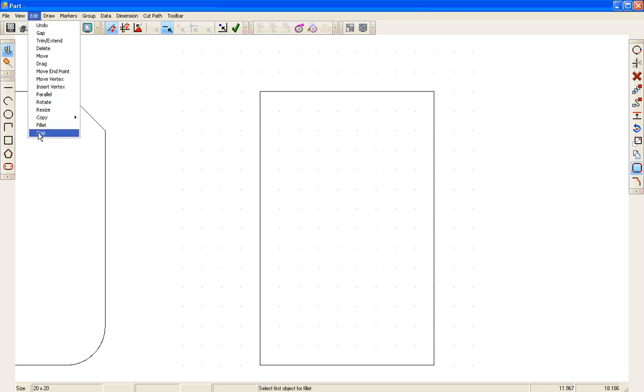The last thing in the edit menu is snip. Imagine you have a virtual pair of tin snips. Okay? And we want to place a V-notch in this blank. The first snip point is always going to be on the outside. The second one is always going to be on the inside. And the third one, again, is always going to be on the outside. Notice I was placing that in a V fashion, and it gives me a little V-notch right there.